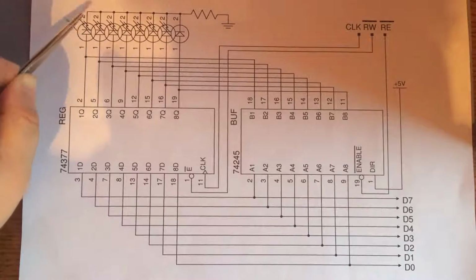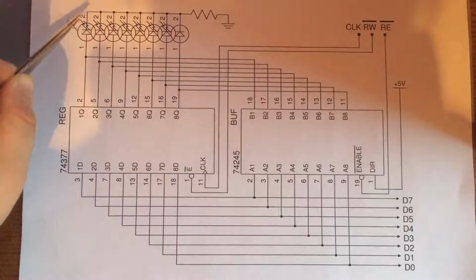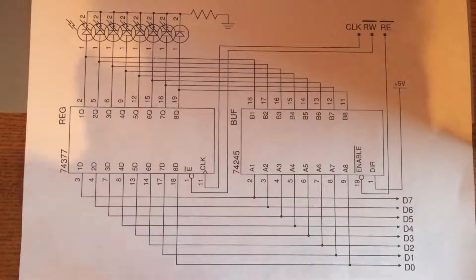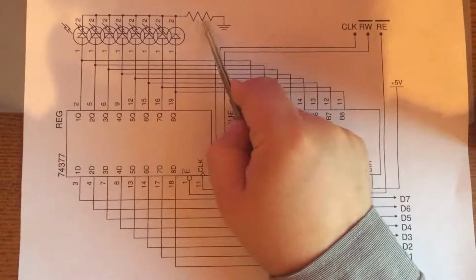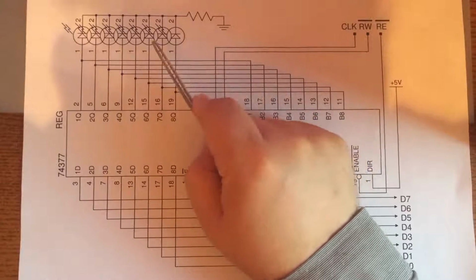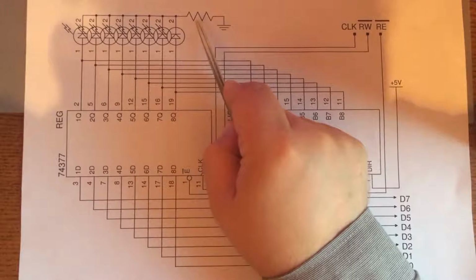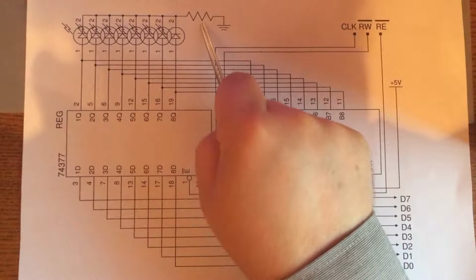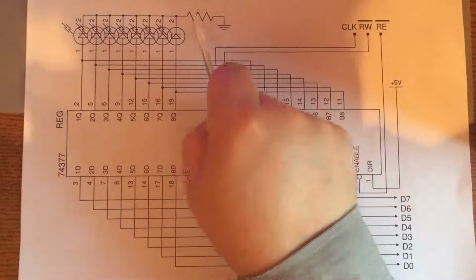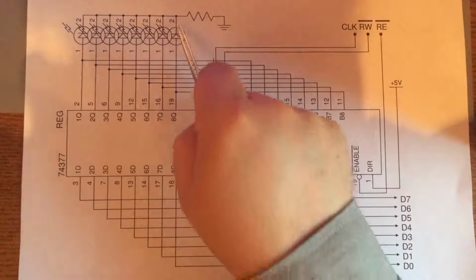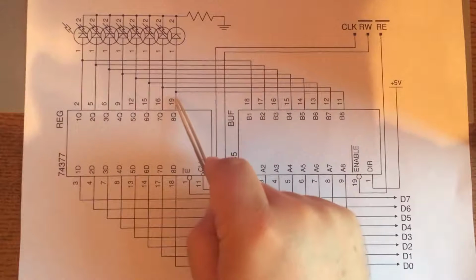One way would have been to add a resistor to each LED, and then I could have controlled the current precisely for each LED. But I haven't done that because, as we'll see on the physical layout, that's a little bit cumbersome to do. So I've used a single current limiting resistor which all the LEDs on the register share. And that has one interesting side effect. Because I have a single current limiting resistor, I'm basically determining what the current will be through that resistor. So if these are the red LEDs, they're going to drop, if they're on, about 1.8 volts. And up here, we're going to have, let's say, 5.